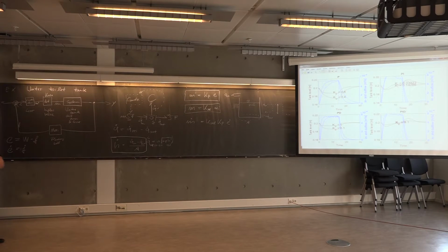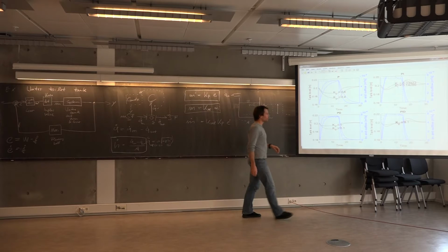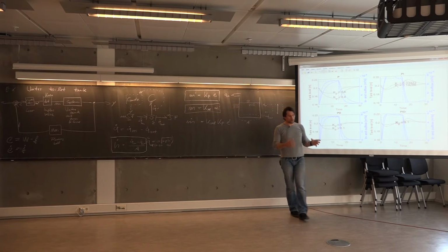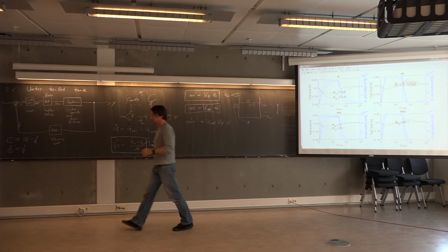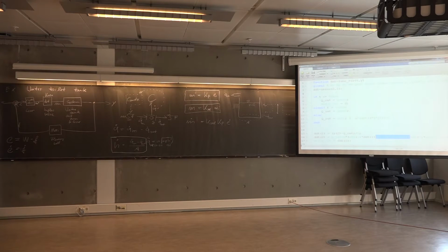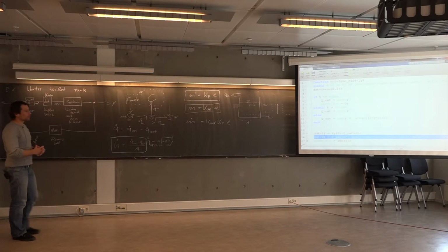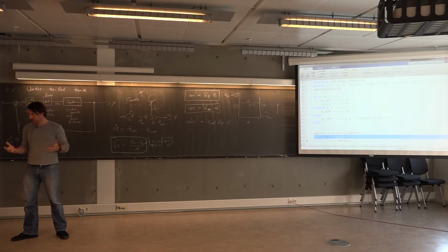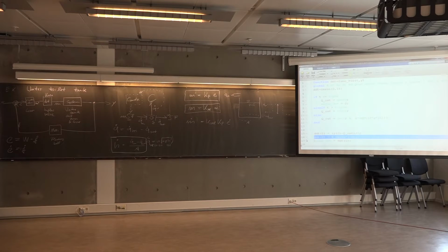Now, I was a little bit too fast with the last example. The fourth subplot here is this PID controller, where we have all three terms as just mentioned in the controller equation. If we jump back to the function file, it's basically the whole equation which is being considered for this fourth subplot. It's just a combination of all the previous ones.